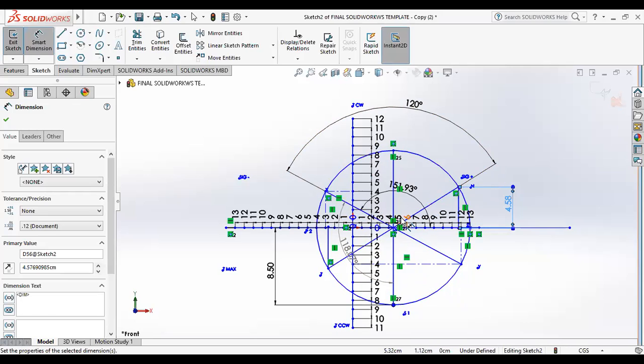Then what you have to do, this point where it meets the Mohr circle is the n axis and the other point is the t axis. That is the n and t axis, the normal and tangential axis. That is, sigma normal consists of sigma x dash and tau dash. Sigma tangential consists of sigma y dash and tau dash. Sigma x dash is given by this point. But we didn't calculate sigma x dash and tau dash, we calculated sigma normal and sigma tangential. Sigma x dash is given by this horizontal measurement.